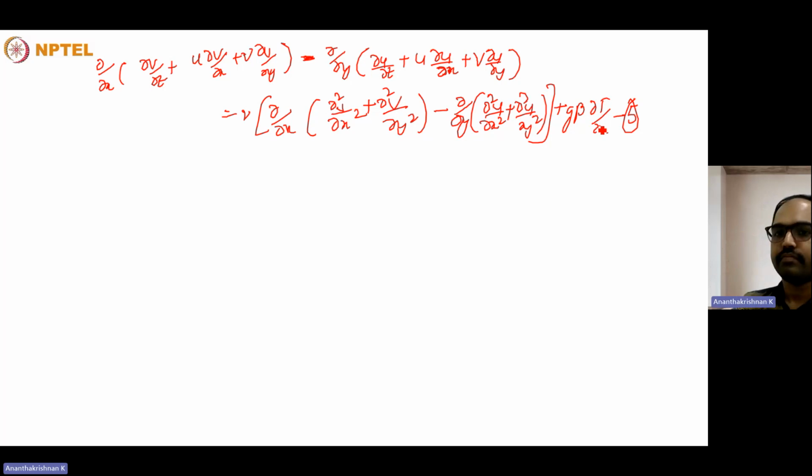So this is the equation that we can get by combining x and y in a different manner, differentiating x momentum equation with respect to y and y momentum with respect to x, and we try to eliminate pressure out of it. But even then, there are three unknowns, U, V, and temperature, and we have only two equations. So what we could try to do is that we can use scaling analysis to determine